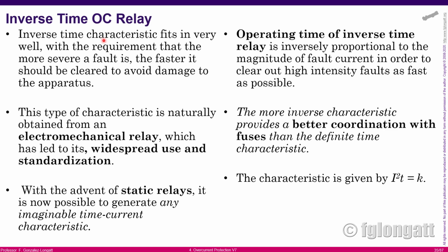If we have a massive short circuit current, the relay will work extremely fast. But if the short circuit current is not so big, the relay will take some time, and that time will be defined by the inverse of the short circuit current. Okay, so more or less.